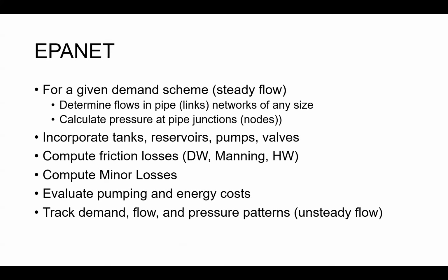And it's also useful under unsteady flow conditions where you're tracking demand, say demand's changing hourly over a day, and looking at where you might have critically low pressure and discharge times or high velocity times under high demand scenarios, and optimizing your system to work for both steady state and peak conditions.